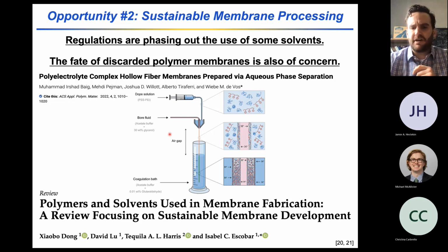And so there's some exciting work to try and address these ideas. I think Isabel Escobar has a beautiful review, and Wiebe de Vos has a really interesting idea where you can dissolve polyelectrolytes in an aqueous casting solution, and by manipulating pH or other aspects, ionic strength for example, you can do an all aqueous phase separation based process.